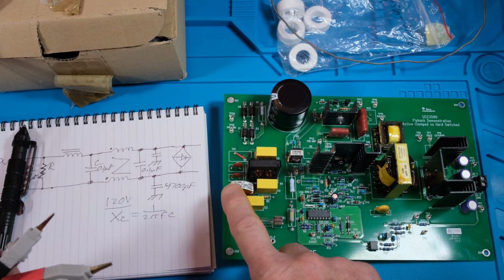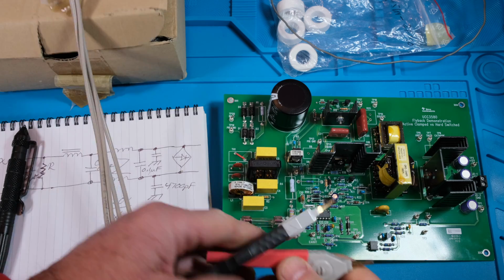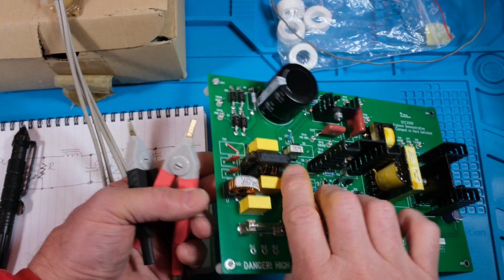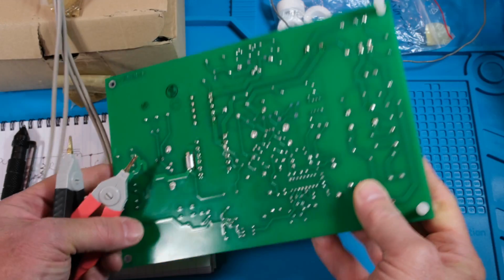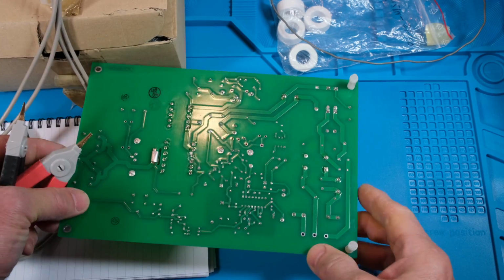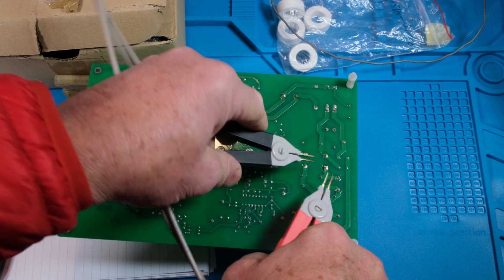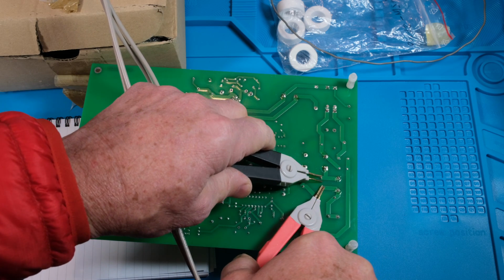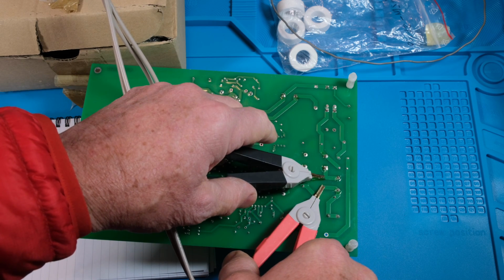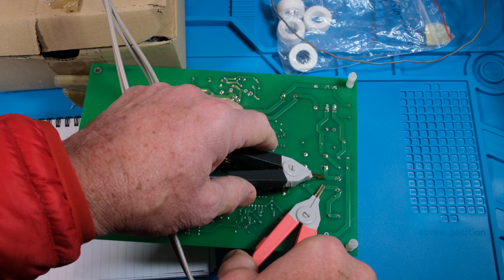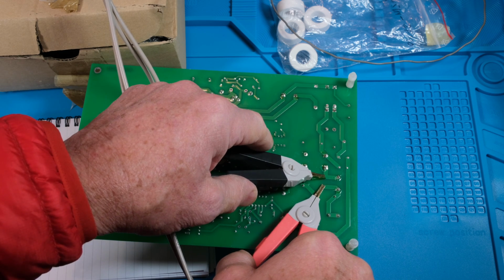All right, so what is the value of these things? I've got my LCR meter. Here, let me just flip it over. Okay, we're going to measure this guy first. It's right here, those two pads, right? So this is in circuit, so maybe not 100% accurate, but pretty close. I'm getting about 22 microhenries, rounded, okay?